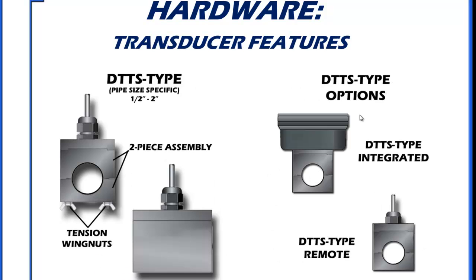Less than 2 inches, the transducers are pipe size specific. So if you had a 1/2 inch copper, you'd have one pipe size, because basically the dimension is this hole right here. It breaks apart like a donut, and you put together with some wire nuts there to hold this C configuration, 2 C's configurations together. But this diameter here is very specific, much like, say, a magnetic flow meter there. So if you had a 2-inch meter, we'd say, is it copper? Is it an ANSI pipe? It'd be a different pipe part number. Price points are less than the 2-inch or larger.